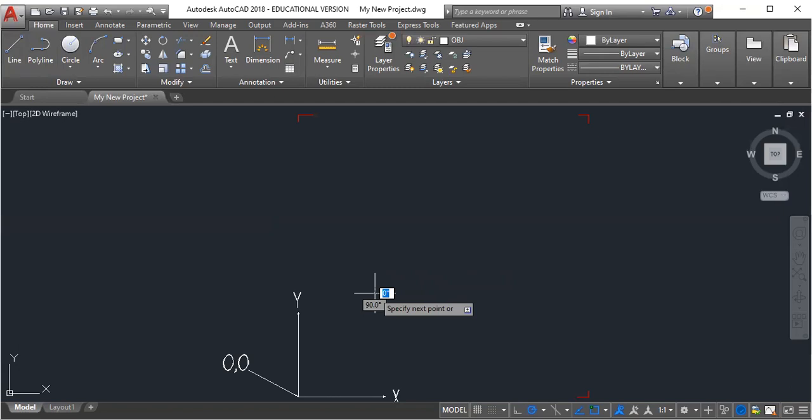And if you see, as I start to draw this out, it's establishing a line. And that line is established using what we call polar coordinates. So the origin of this line is at the place where I clicked. But if you take a look, not in the blue box, but the gray box, it's showing a count in degrees, starting at 0.0 degrees. And as I move counterclockwise around this, you can see the number of degrees rotating, and watch it snap in at 90. And I rotate it down, it's going to snap in again at 180, and so forth.